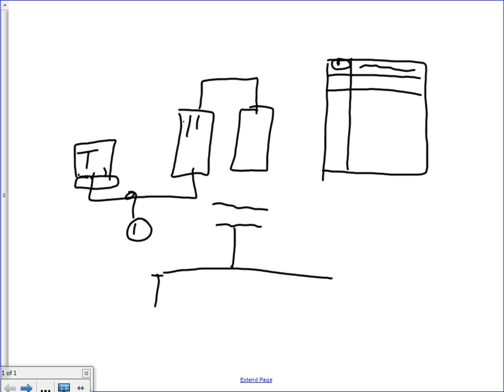This is H and this is L, so this bus would be panel H, and this other bus would be panel L, and you would show the breaker in panel H, right in this location, that feeds panel L.